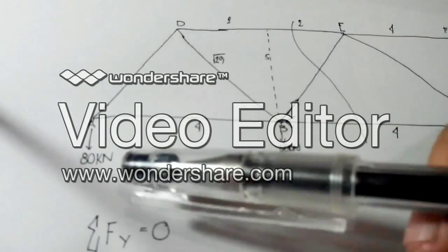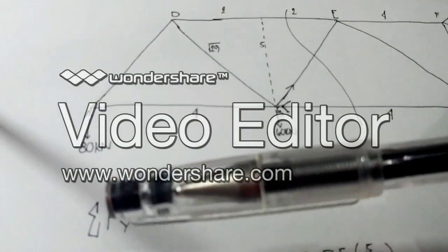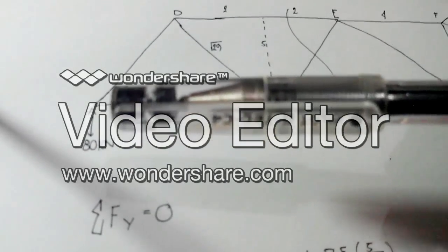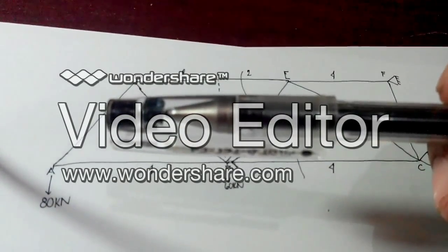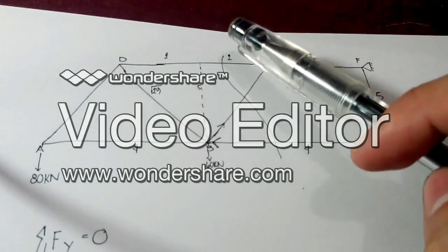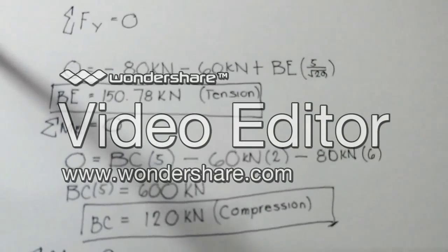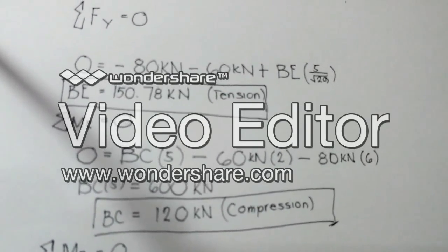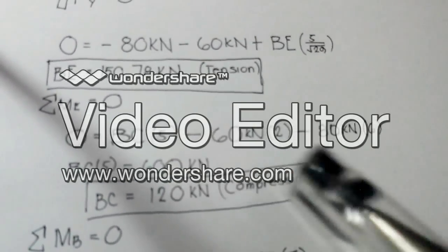And finally, the force on A also rotates the truss counterclockwise, so it's also negative. Its perpendicular distance is 4 plus 2, it's 6. So 0 is equal to BC multiplied by the perpendicular distance of 5 minus 60 kilonewtons times 2 meters minus 80 kilonewtons times 6 meters. So BC will be equal to 120 kilonewtons.